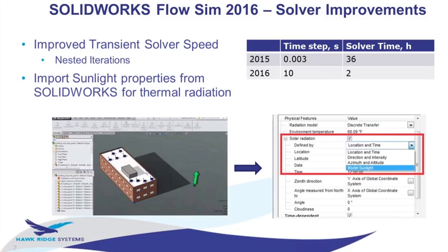And that meant that if you had, let's say, a problem of a box heating up with some components in it, or really any kind of thermal cycling or other effects, the length of time for the analysis might be 6 hours. You know, you want to simulate something running all day or sitting out in the sun all day. And so the solve time would be very high because, again, the time step would need to be small to see what the air currents are doing.